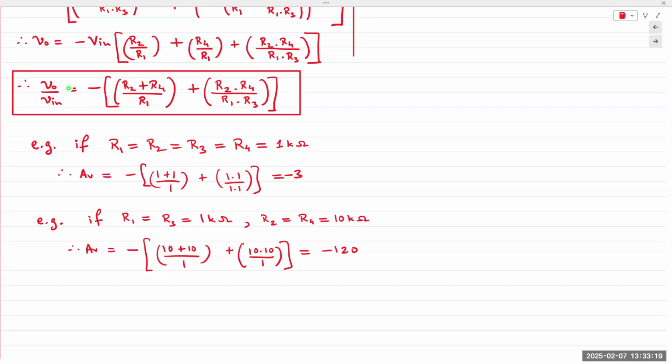But if you want something large as your gain, right? Let's say your input signal is very small, 10 millivolts, 50 millivolts, very small input signal. You want a gain of like hundreds. If we use a large resistor in the feedback path, the current through there is going to be small, so the circuit won't work. I mean, theoretically it will work, but practically speaking, it might not work. If you want a gain of 100 and you plug in a resistor of 100 kilo ohms in the feedback path, the current will be very small. Your theoretical gain would be 100, but your circuit may not work as intended.